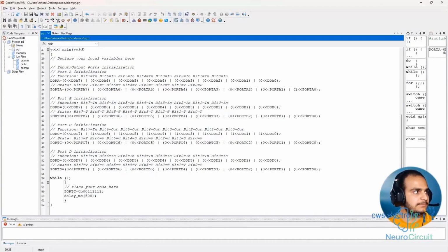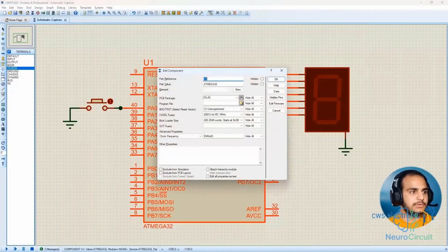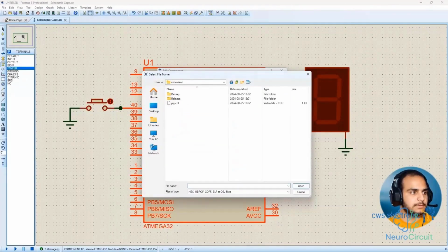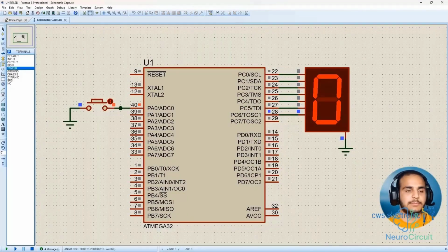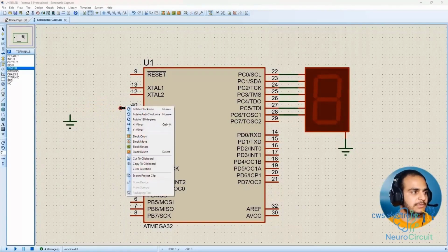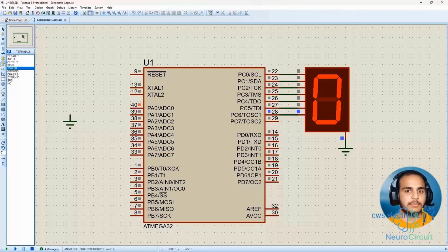And now, if we upload the code to the microcontroller, it will display the number 0 for us. Here, we can also see that the pin with the pull-up is set to high, meaning even if I don't connect anything to it, we see that this pin is set to pull-up mode, and in the real world, it won't pick up noise anymore.